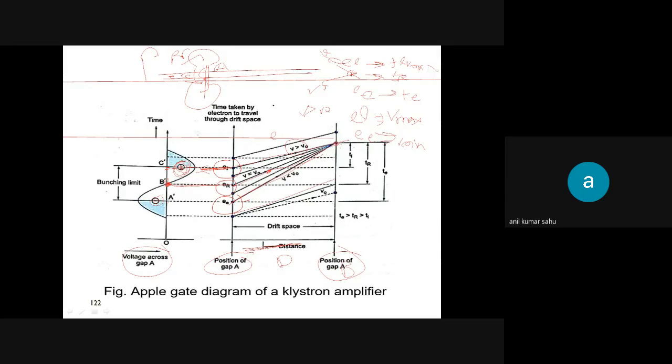Similarly, the late electron is emitted from the electron gun too late compared to the reference electron as well as the early electron. So here it interacts with the positive RF input. The velocity is accelerated because of this positive field and is going to be increased, so that the velocity of the late electron is much greater than the velocity of the reference electron.